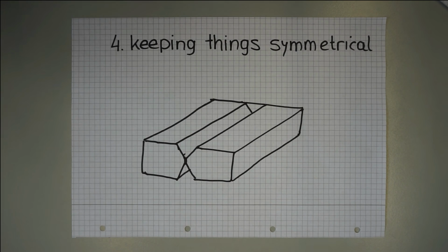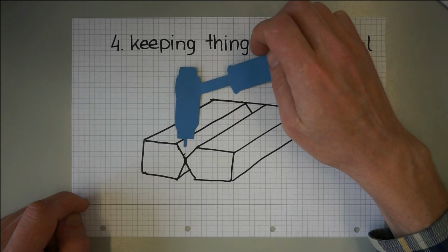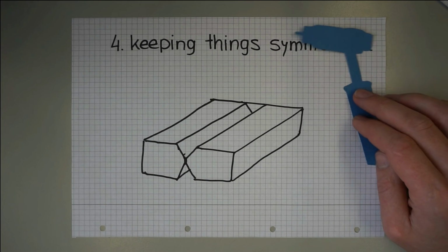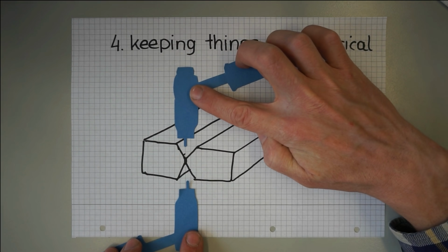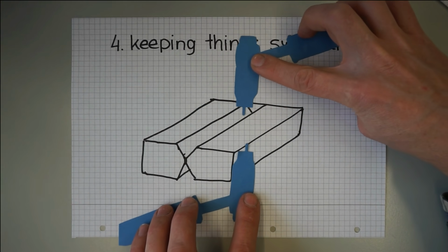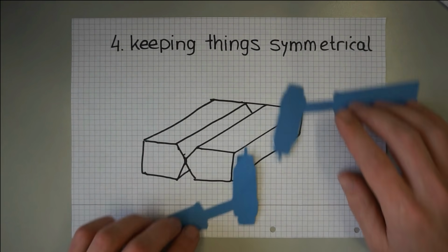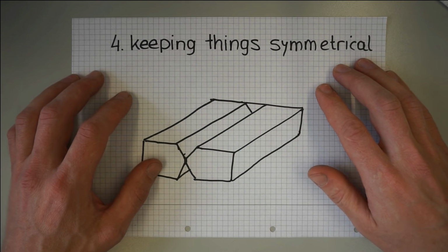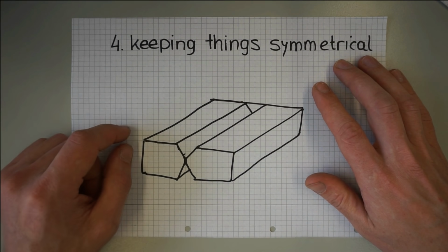Consider this example here, and let's say that we have to weld this workpiece from both sides. We could do this the conventional way and weld first up here and then down there. But if we want to keep things symmetrical, we could also have two welders weld on the top and bottom side synchronously in a way like this. This way, however, we can only minimize bending or curving distortion. Shortening or shape-changing distortion cannot be avoided this way. In other words, this way we only can keep the workpiece symmetrical.